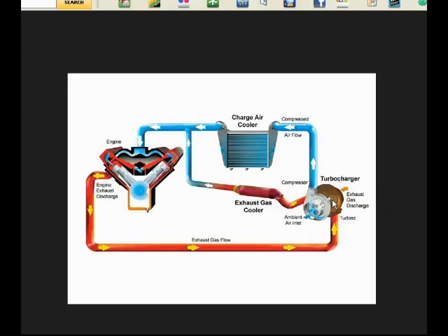And this turbine in here then drives the compressor to draw in ambient air from the outside, and then it compresses it through a centrifugal compressor disc to a diffuser, and then out back first through an intercooler, which, remember, when you compress the air you get heat. You might get a several hundred degrees temperature rise from that compression, so it's got to go through an intercooler to expand and drop the temperature, and then bring that pressure back up into the engine, to the intake, because you don't want too hot air going in, but you want some temperature rise.